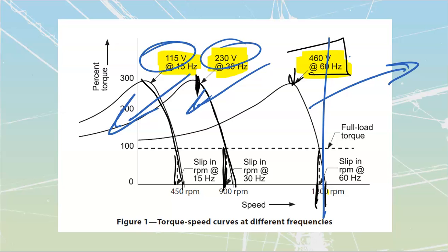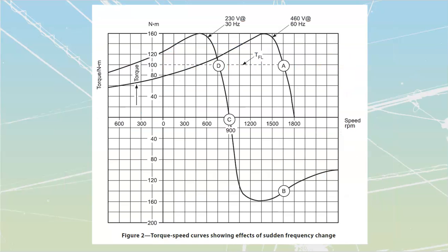Braking of any type of motor is going to be automatic when we look at regeneration, right? Dynamic braking was where we were going to take a motor, use the inertia of the rotor as our prime mover, and turn the thing back into a generator, so to speak, and dissipate power across a load. Regenerative braking is where we are going to push that power back out into our circuit.